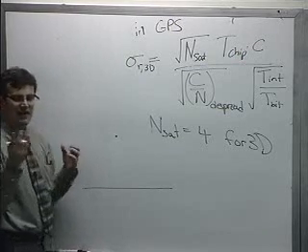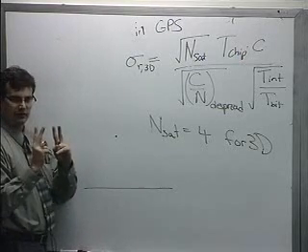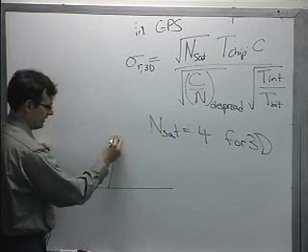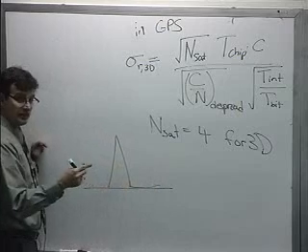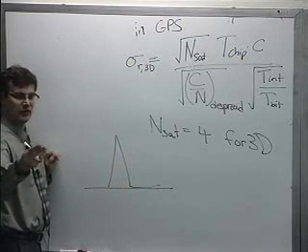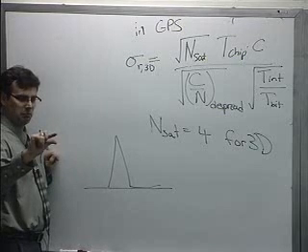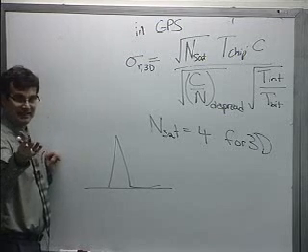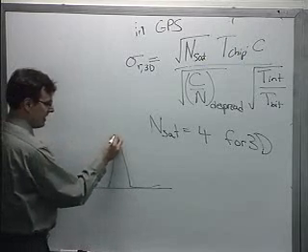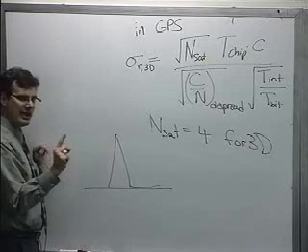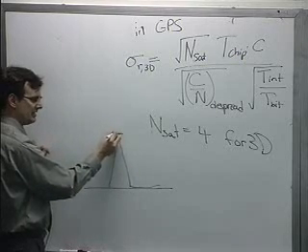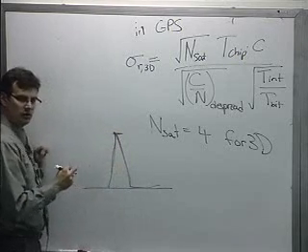Think of it this way: if I have another correlator in my receiver, and I have a clock that's clocking it faster than, or has precision well beyond, my sampling range, an internal clock to my receiver, then I can actually get a crude estimate of where within a chip this peak was.